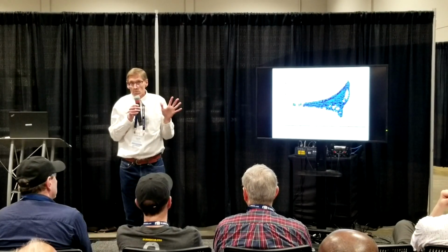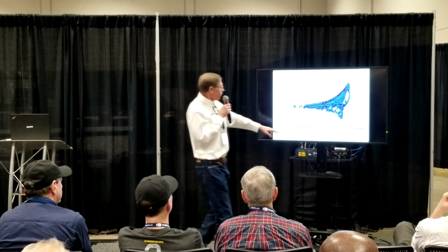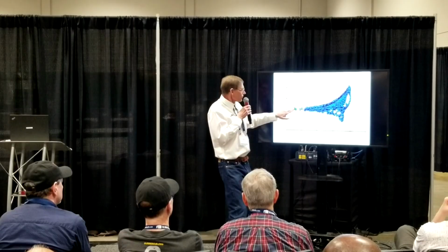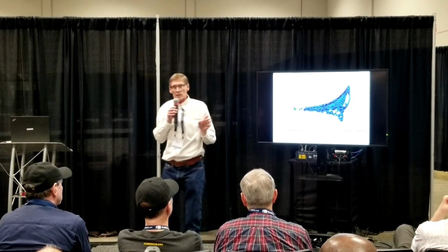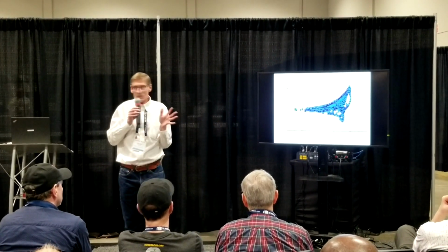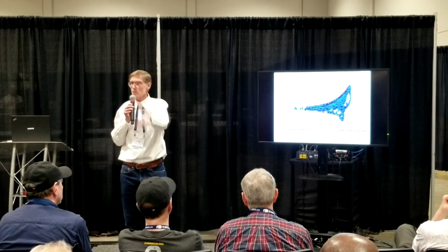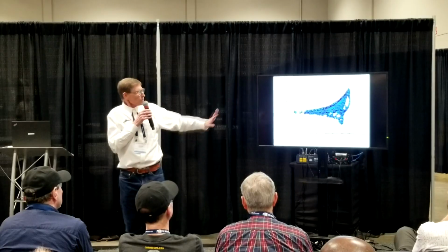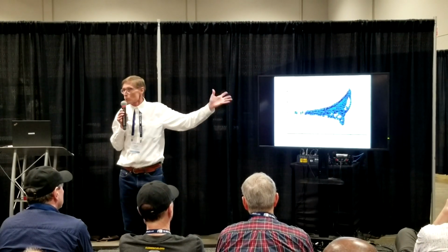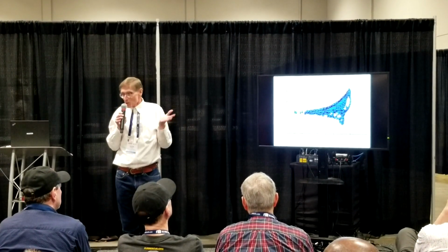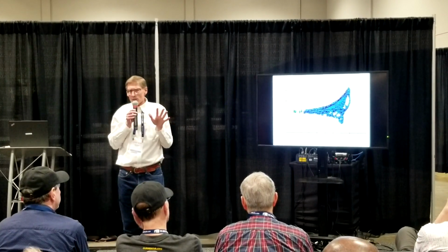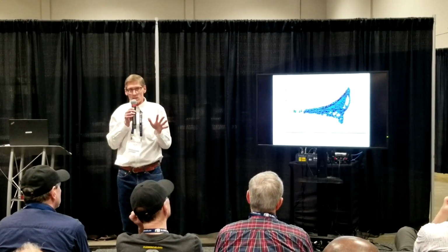Is that true? If that were true, why do I have some of this signal reflected back off of the load? Because if the cable was truly 75 ohms resistive, nothing would reflect off of a resistor. It would all be dropped across the load, but it isn't. So this is really a measurement of how much we've screwed up making the cable. I mean, it literally is that. So in other words, our coaxial cable is not always resistive.